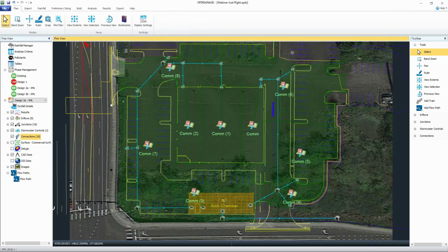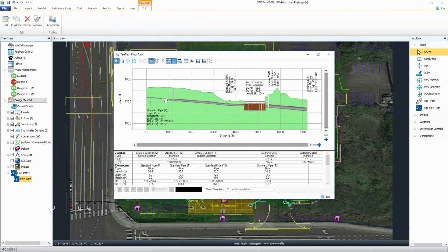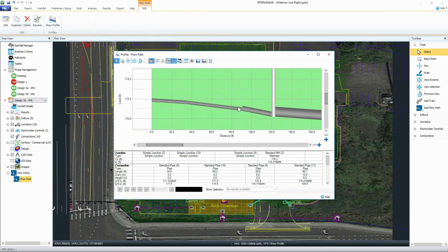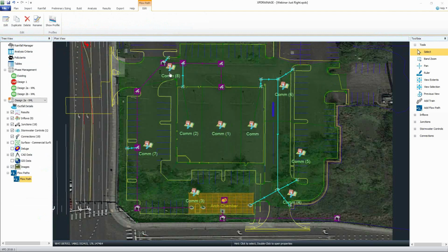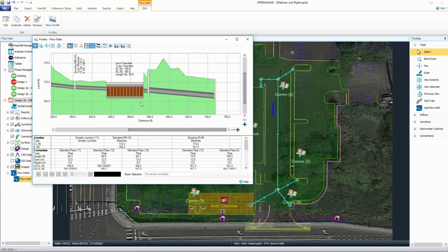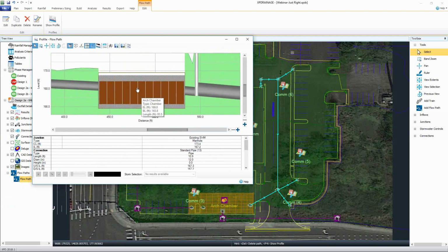Okay, bring in your pipe network. In this case, I have 2 different phases that I'm playing with where I have imported a pipe network. And just for the sake of time, I'll jump right into what this looks like. So here, we'll see if we can zoom in, we have this pipe network. It's pretty small in size. So we can see here a 4-inch diameter roof lateral, this magenta line. So pretty common, you have a small roof lateral coming off. Pipes get larger as they go downstream, which is a good sign. Here are the chambers that I was playing with before.